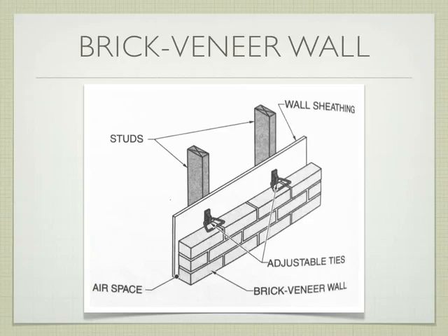So in this particular example, it's the same kind of brick veneer wall. This time we're against just regular standard wood frame construction. I recognize certainly that this wood frame part means nothing to you yet, unless you've worked in the construction field a little bit. We will cover this eventually. Same concept here. We have these little ties that are attached to, in this case, the studs, which are the primary wood structural elements. They're attached there. These then basically get embedded in that little mortar joint and tie the brick to the wall itself.